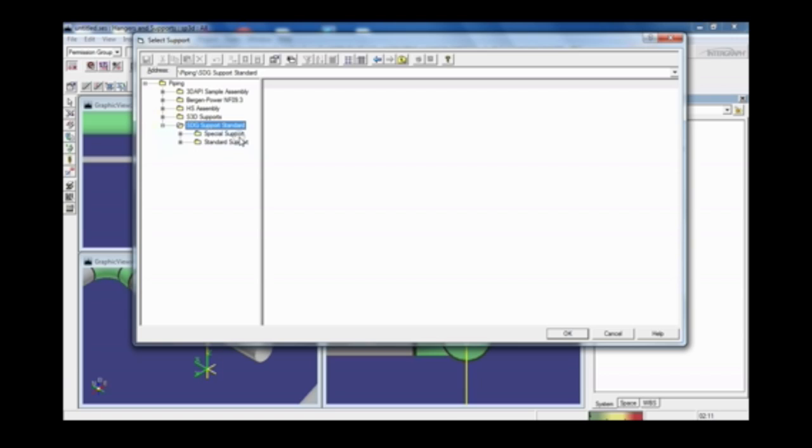If you get into the special supports, you will have a cryogenic support, which is a subdivision of the special supports. The same way, if you get into the standard supports, you have subdivisions called A index, G index, PS index, S index. That means A stands for anchor index, G for guide index, PS for pipe supports, that is channel supports, and S index is obviously the shoe index. We are taking the example of this one, which falls under the shoe index, and that is why they call it S-601.